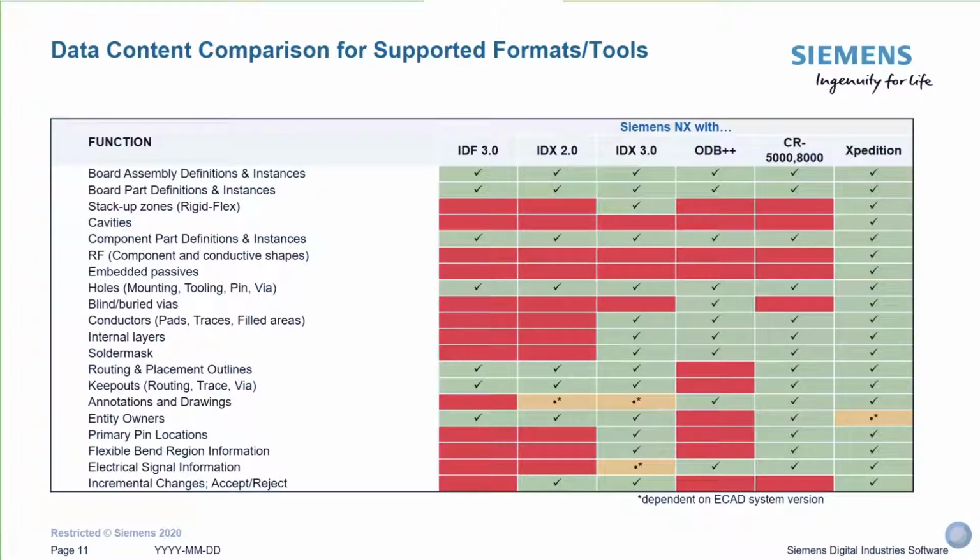That would be the IDX3 in our case, the ODB++, our Zuken interface, as well as our Expedition integration. All these 4 formats allow you to perform precise and efficient thermal analysis via PCB Exchange.